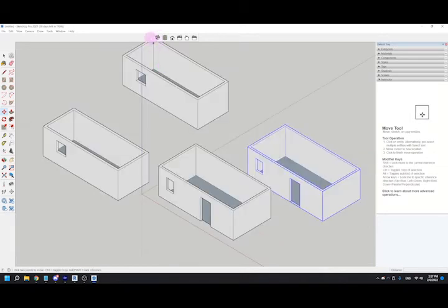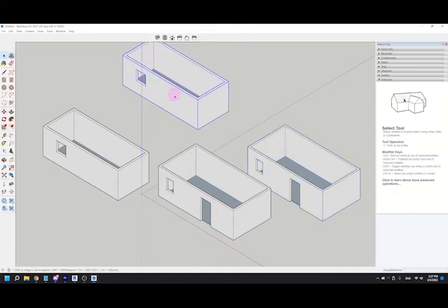And then we'll put ourselves into a 3D view, isometric. So I've got 2 copies of this group and 2 copies of this component. Since they both operate with that same rule, you can't edit the feature without being in it, what's the point, or why should I choose a component versus a group?